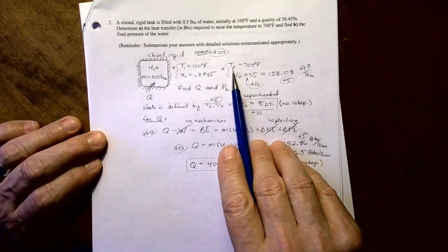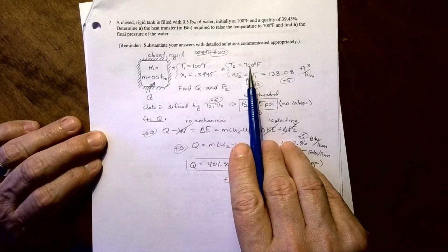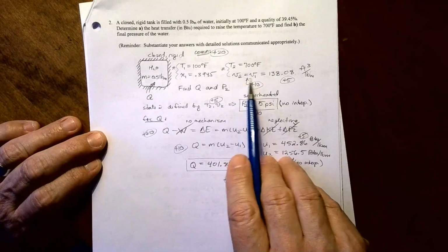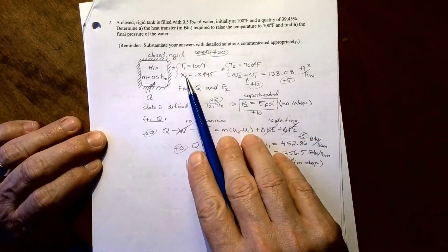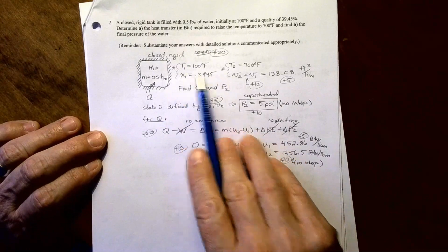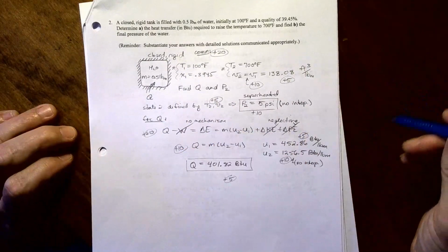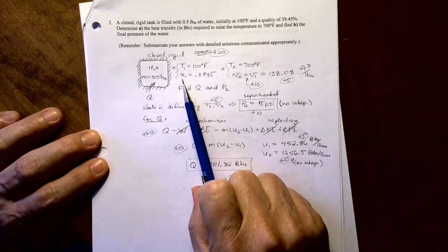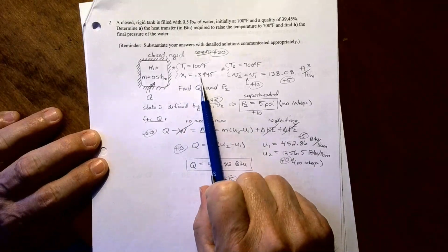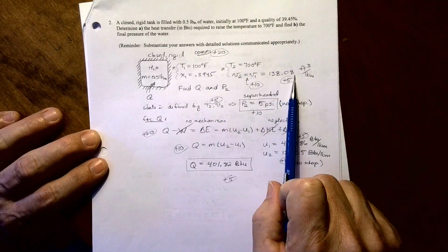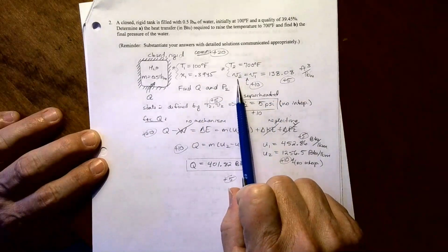And then it says also find the pressure of the water at state 2. They only give us the temperature at state 2, but if we recognize that the specific volumes are going to be the same, so v2 equals v1, and for v1 we have two properties, so that's defined. I put a little star here: both states are now defined. I went ahead and calculated v1 with this quality and ended up with 138.08 cubic feet per pound mass, so that's also v2.